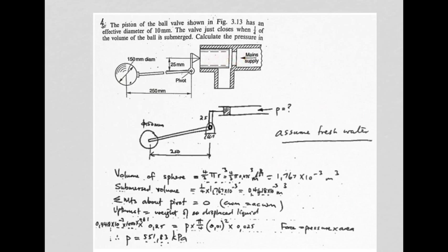force from right to left, and that is counteracted in perfect equilibrium with the upthrust from this buoyant sphere on the end of the arm. And if you get the ratio just right, then you can achieve perfect balance and you can block off this water supply. If the level of water in the cistern drops, this ball drops and it allows this piston to move off its seat and allows a little bit of water in and refills the cistern. And as we know, the automatic process continues and the ball rises until it blocks off the system again and you maintain a water level in the cistern.